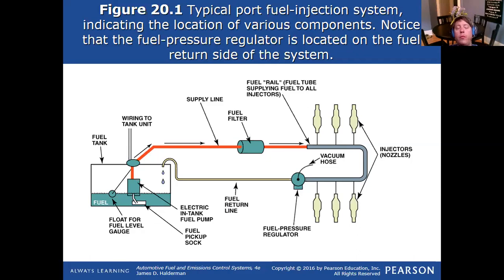We can control that fuel pressure at the tank, and all of the fuel that comes down the pressure line is already set at the correct pressure, and it's also set for the correct volume based on the engine load. And so we can eliminate just a redundant fuel line. That does a few things. That's good for overall cost of the manufacturing process of the vehicle, but it's also good for safety, because we have one less fuel line that can rupture in an accident.